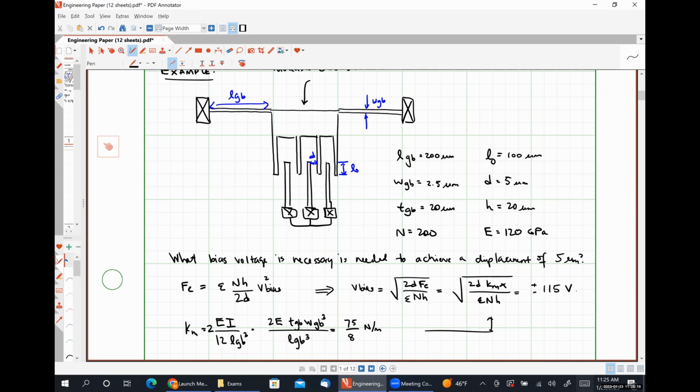So it literally took years of iterating on this basic design in order to get that. So the largest advantage of this scheme, particularly with its applications to radio frequency MEMS and variable capacitors, is that you can get a much more extended tuning range, and you don't have to worry about the pull-in effect.